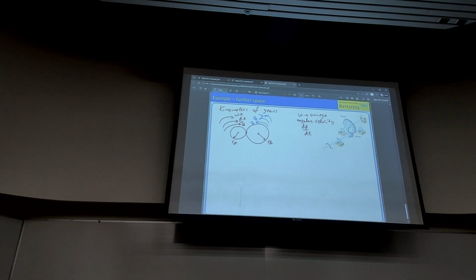All right, I always derive these from scratch, easy to do. So start from here. Imagine the teeth that are in contact: this is the angular deflection phi A, and this is the angular deflection phi B. I reason that this arc length at contact is the same whether you view it from the left or the right.